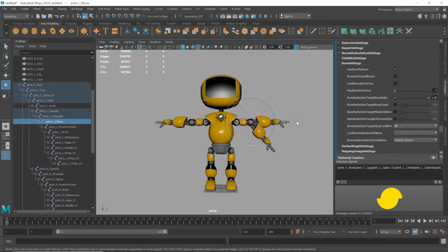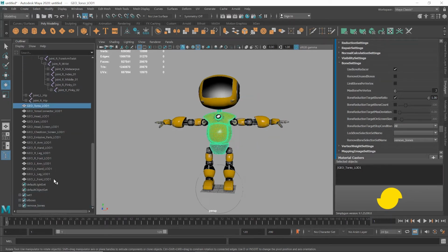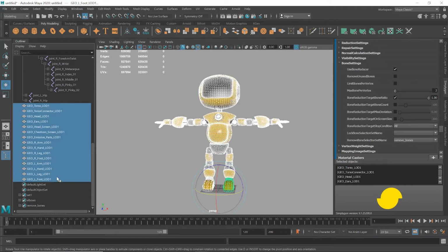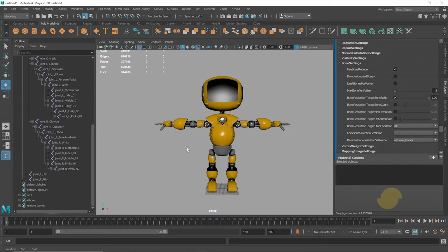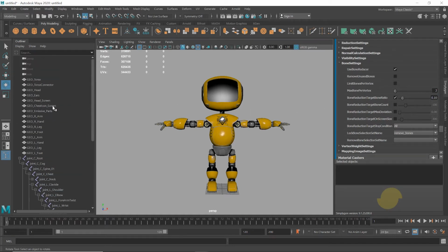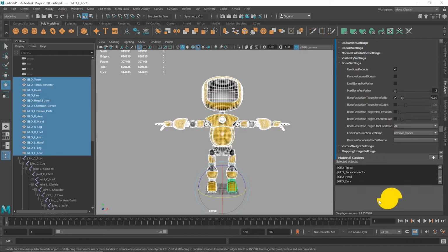If we undo that, we can have a look at manual bone protection. In order to protect bones, we use a selection set once again. Instead of selecting it in the Remove Bone Selection Set Name dropdown, we will choose this set under the Lock Bone Selection Set Name dropdown. In order to really show the effect, I'll set the bone reduction target bone ratio down to 0.1, which will aim to keep only 10% of the bones. Now we can run the reduction.